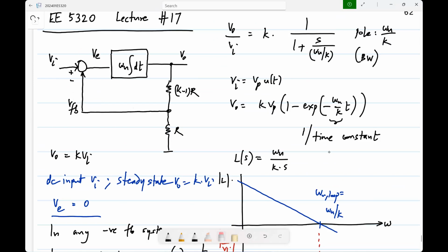Okay, so that input network of the negative feedback system, where you are essentially computing this error when you are doing this comparison, has to be done precisely. Okay, after that it doesn't matter, you can drive it slowly or rapidly and so on. Because the result of that comparison is what will be driven to 0. This is very clear, right? If you are driving and your speedometer has an offset, you will be driving at the wrong speed. It's not that you don't know how to drive, but it's basically that you are comparing whatever the speedometer reads to the desired speed. Okay, this is fine. Any questions?